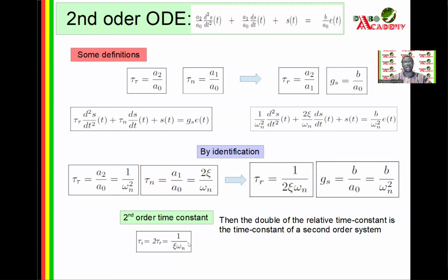Even if you resolve as in traditional control, as I presented in the beginning, yes, the traditional control system I have studied also says that you have different time constants according to the damping ratio that you should calculate. Let me say it again. If you have the damping ratio less than 1, you have two complex conjugated time constants. If you have the damping ratio equal to 1, you have double time constants.